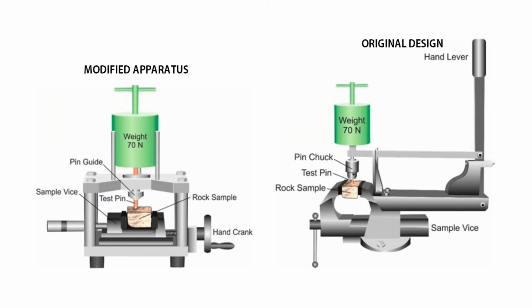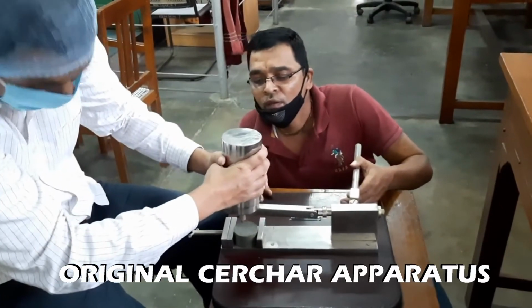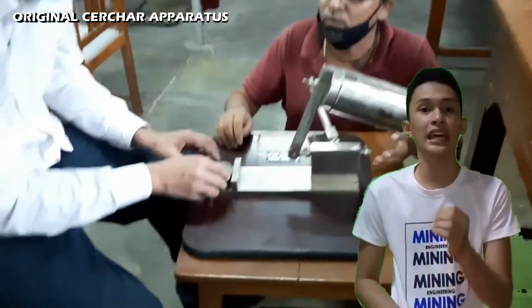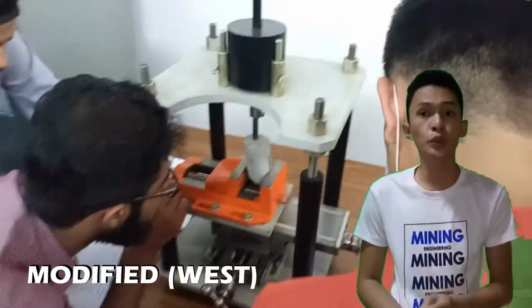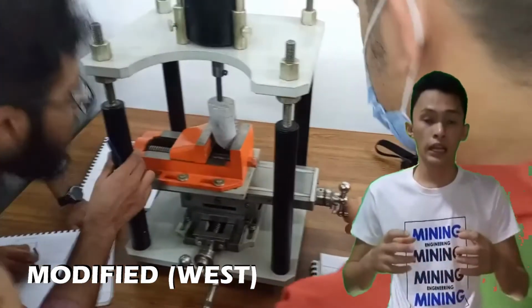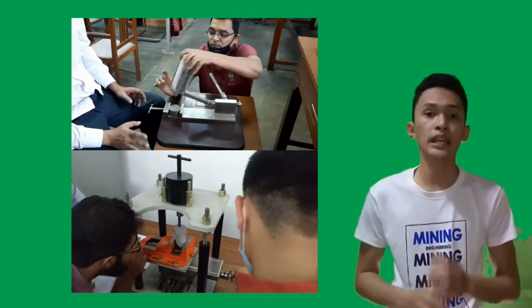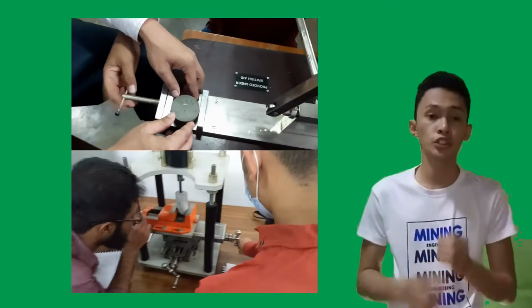The main features in the design of the two test apparatus and the nomenclature of these apparatus are also offered. A consequence of the difference in design is a near tenfold difference in the test duration between the fast lever actuation with the CERCHAR design compared to the slow screw feed actuation with the West design. Both machines use a rigid vise to firmly clamp the rock sample. It is important to ensure that the apparatus is sufficiently stiff to minimize any lateral movement during a test.